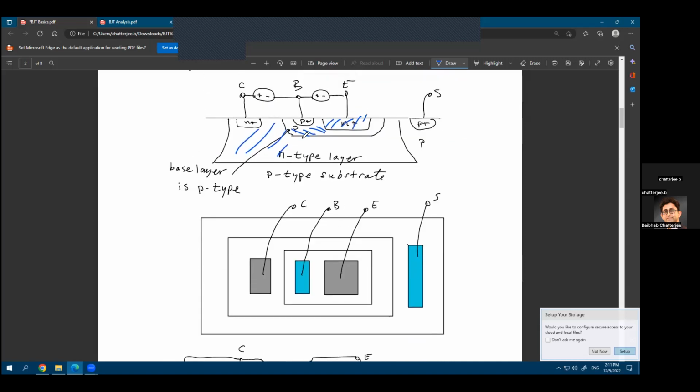Okay, so now this is the overall structure of the BJT. You have the N-type collector, the P-type base, and the N-type emitter. So this is an NPN BJT, right? We'll mostly discuss NPN, which is analogous to an N-channel MOSFET. And the PNP will, of course, be the dual of that, just like a P-channel MOSFET or a PMOS.